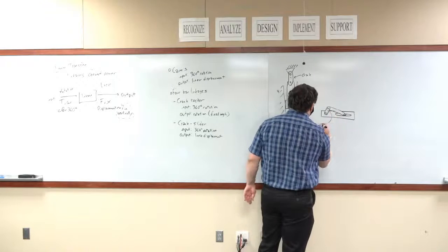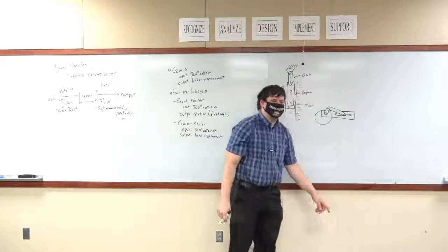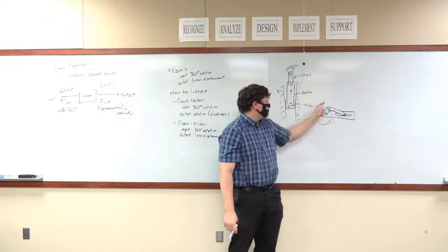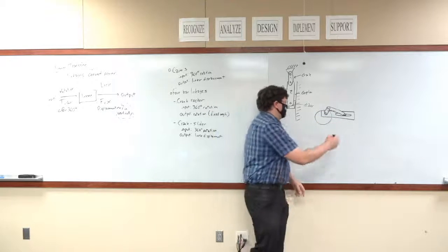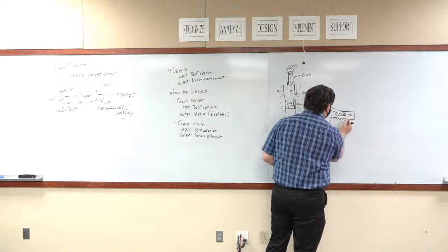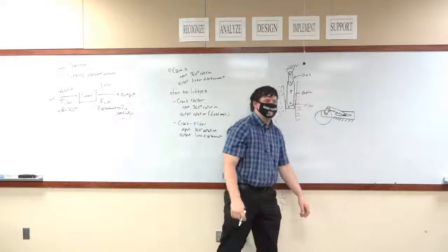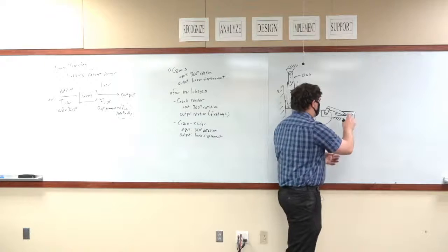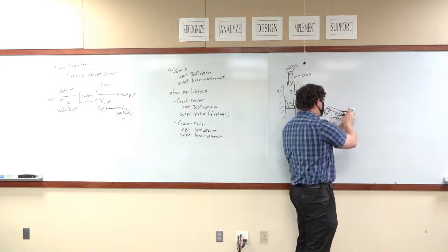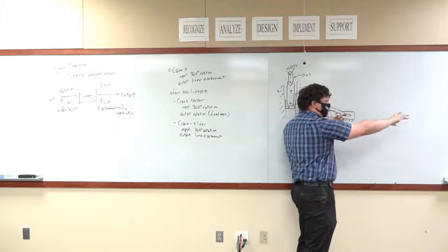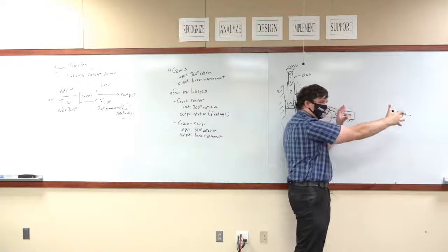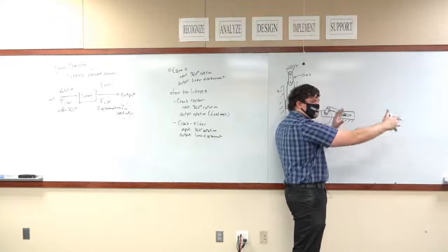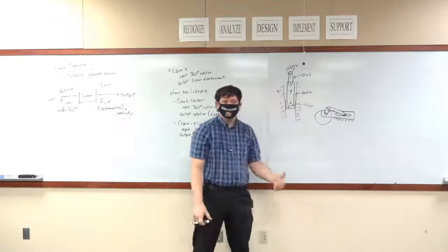And then as this crank travels around 360 degrees, it just slides inside of that. And then this component here would be fixed to ground, okay? You then take this slider, or this bolt here in the slider, and you extrude it out, connect it to the rest of your leg, and it moves up and down like that. Fun times.